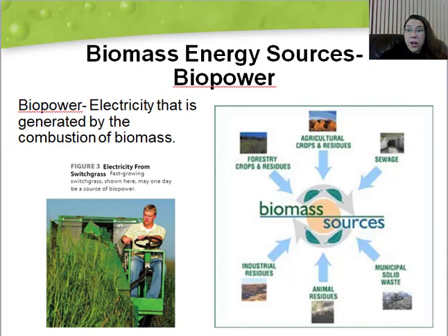The decomposition of biomass by microorganisms actually produces gas that can be used to generate electricity. The breakdown of waste in landfills produces methane. This landfill gas is being captured in many landfills and sold as fuel. Power plants that burn methane and other kinds of biomass operate similarly to those powered by fossil fuels. The combustion heats water, creating steam to turn turbines that power generators. So this is now kind of a recurring theme on how we generate that electricity.